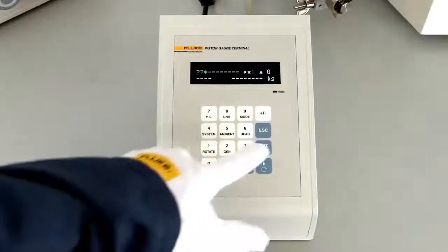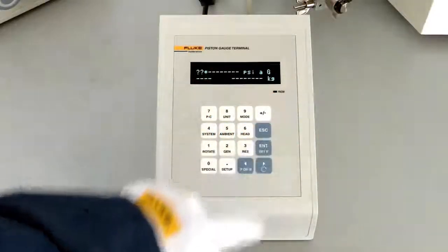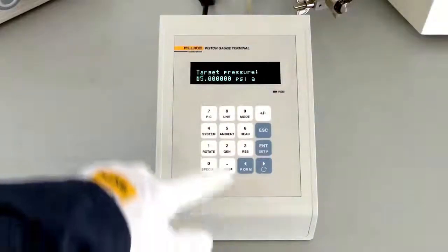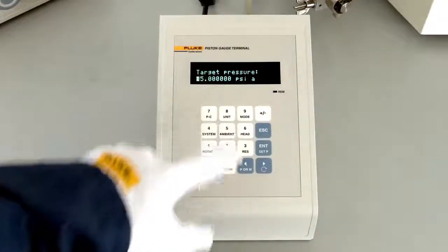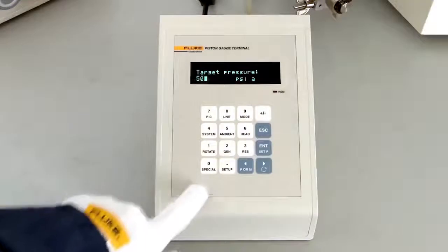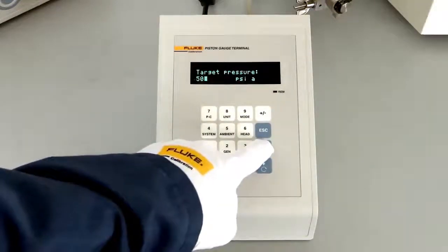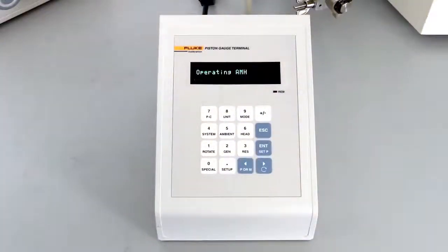The first extreme is to measure each variable that impacts the pressure and perform a full calculation of the fundamental pressure equation. This is the approach used on high-end piston gauges like the Fluke Calibration PG7000 series. By using this approach, with the right equipment, it is feasible for one to get the lowest uncertainties possible.